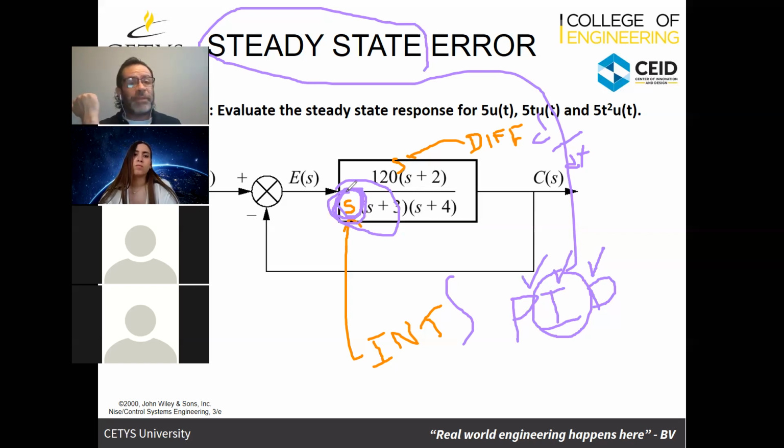I shouldn't move the derivative constant because the derivative constant is for something else. The derivative constant is more used to make the response quicker, and it has more to do with the overshoot and other things. But the I in the integral is going to directly do that. Okay. So I'm getting a bit ahead of myself, but that's where we're going.